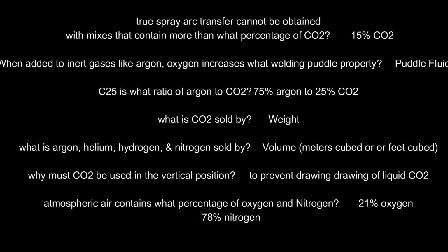What is CO2 sold by? Weight. What are argon, helium, hydrogen, nitrogen sold by? Volume, meters cubed or feet cubed. Why must CO2 be used in the vertical position? To prevent drawing of liquid CO2. Atmospheric air contains what percentage of oxygen and nitrogen? 21% oxygen, 78% nitrogen.